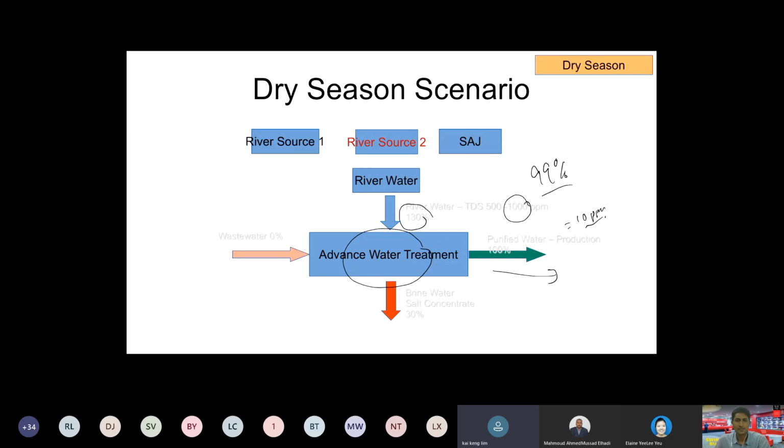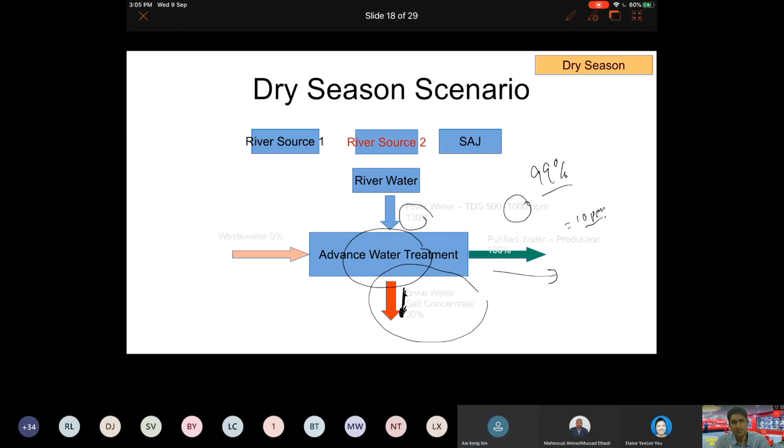If it is the mineral impurity, it is actually rejected at this RO system as brine, which is the concentrated salt. It comes out here. That's why when you have a higher concentration of water source, you need to discharge more brine away. You will have higher discharge of this water. This one is actually thrown away. You're throwing the high brine away because it consists of salt. This is not actually considered a scheduled waste or pollutant.